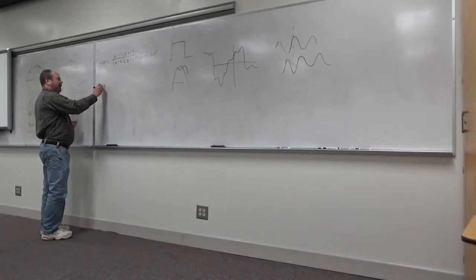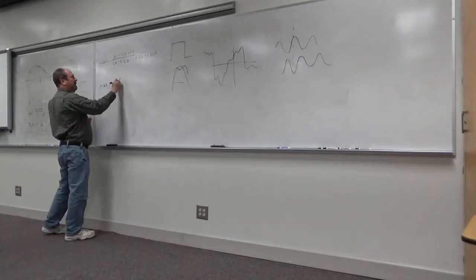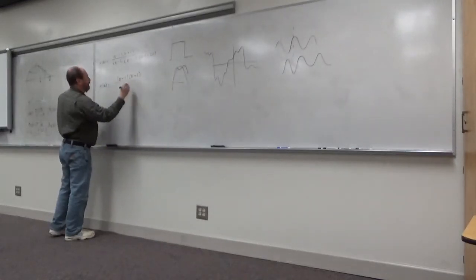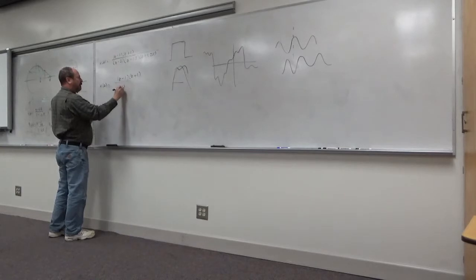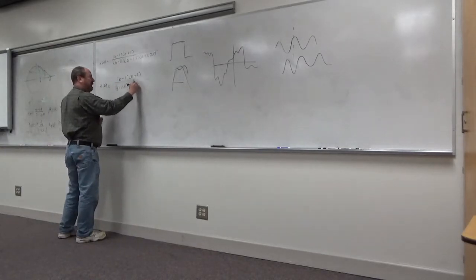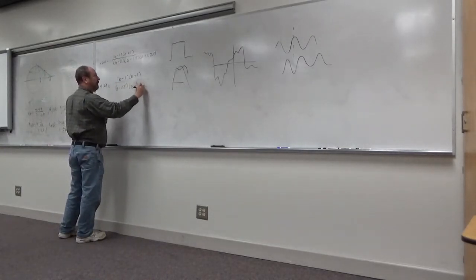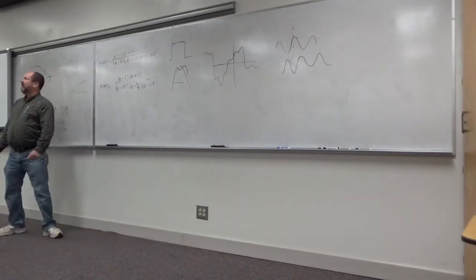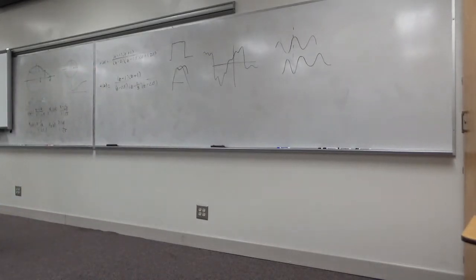I'm going to write another transfer function, z minus 1, z plus 1, and the denominator, z minus 0.5, z minus 2 over 3, and z minus 0.8. Okay? You like the gain response of the other one? This one's got exactly the same gain response. And it's stable. That's right. All the poles are inside the unit circle.